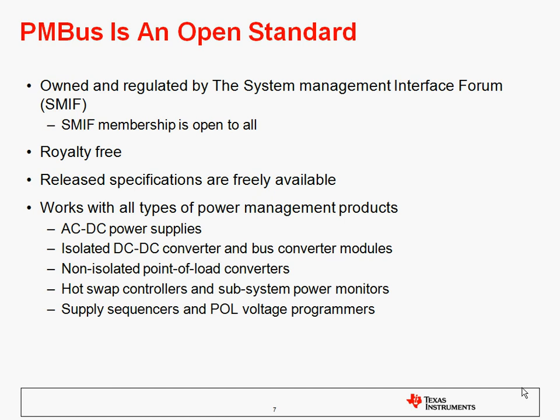And PMBus is owned and regulated by the System Management Interface Forum. It's got open membership to anyone who wants to join. It's a royalty-free protocol. Specifications are available on the website, and it works with all kinds of power management products, anything from an AC to DC or an offline supply to all kinds of DC to DC converters, whether they're isolated or non-isolated, as well as some specialized power management devices like hot swap controllers, power monitors, sequencers, and programmers.